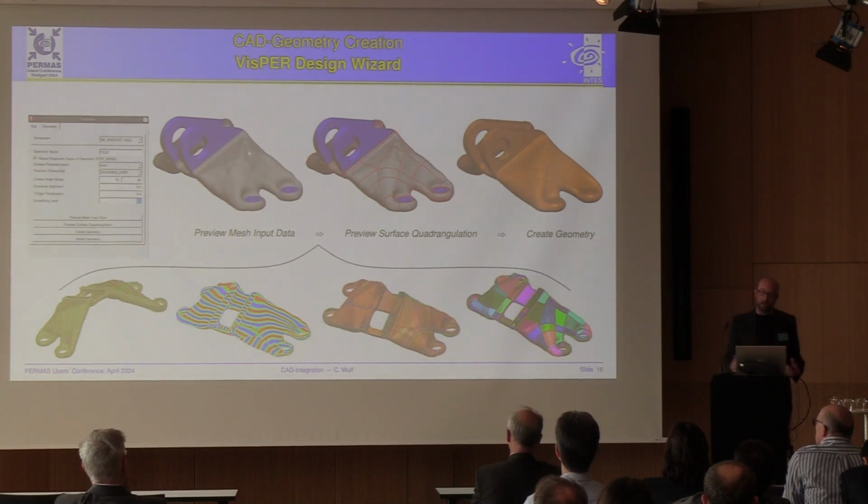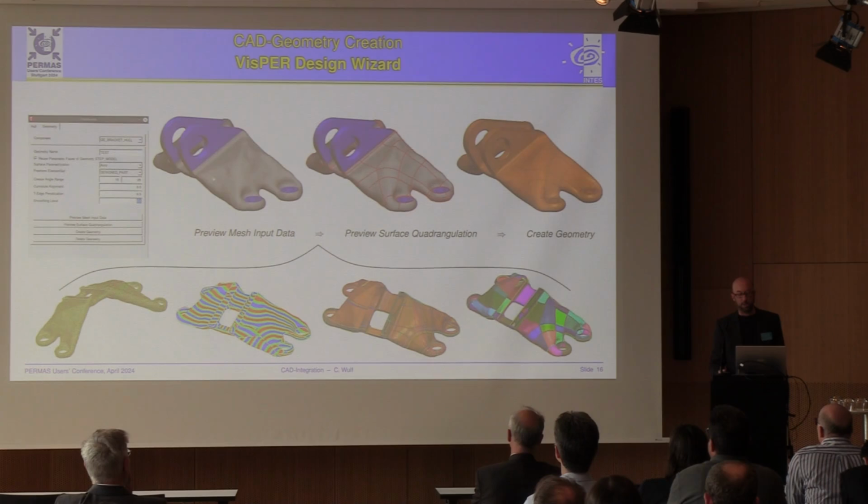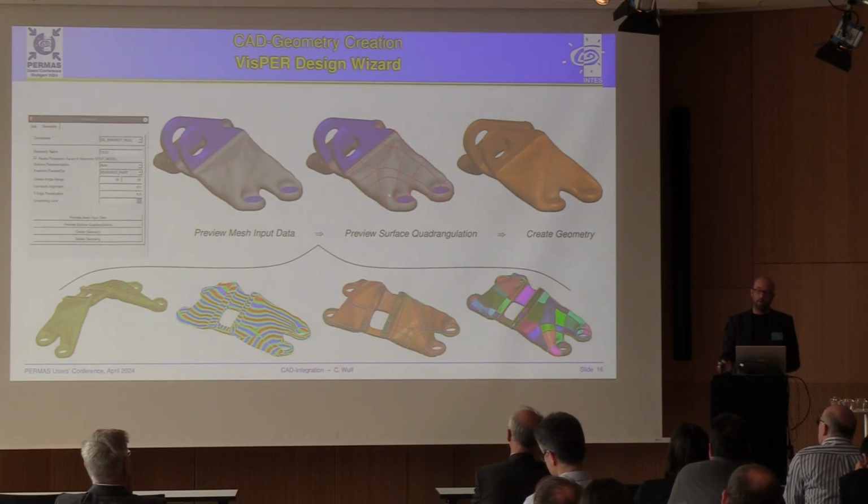This is actually the hybrid geometry consisting of the reused faces of the cut space geometry together with a mesh of the freeform area evolving during topology optimization that should be converted into B-spline patches. Then automatically the quadrangulation is generated.